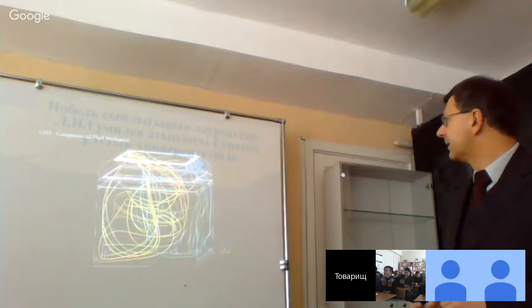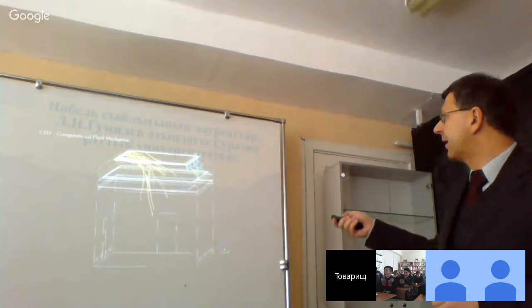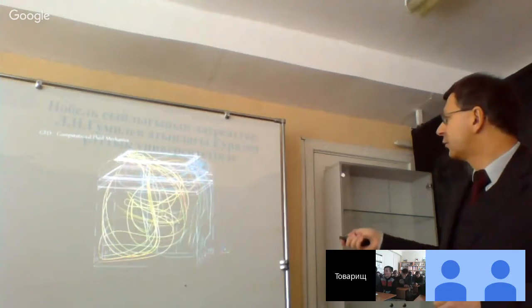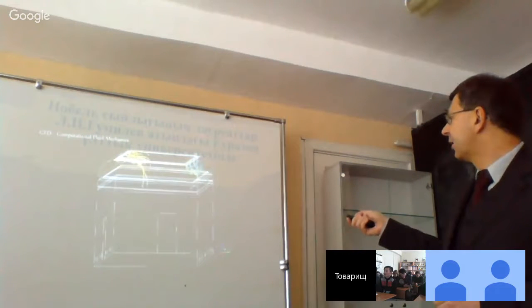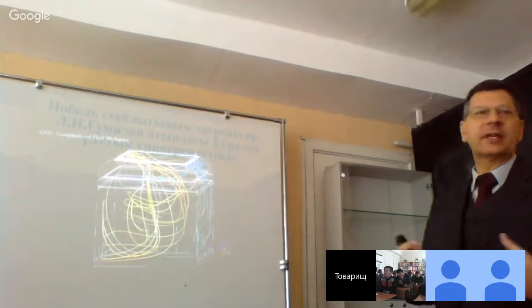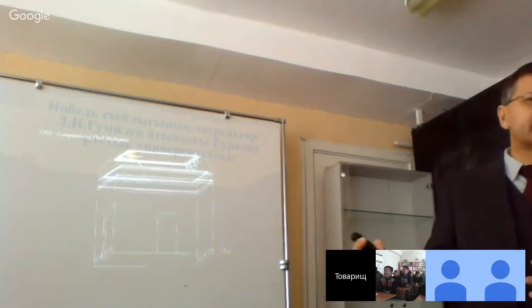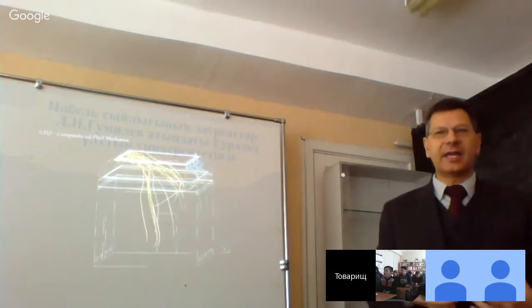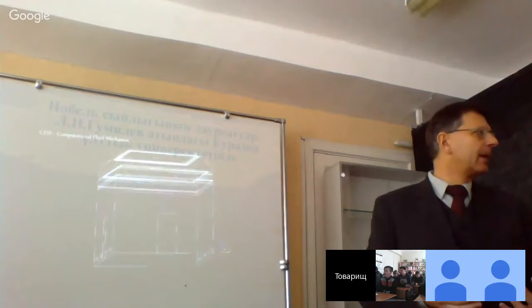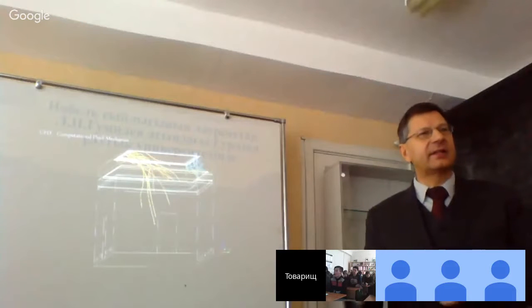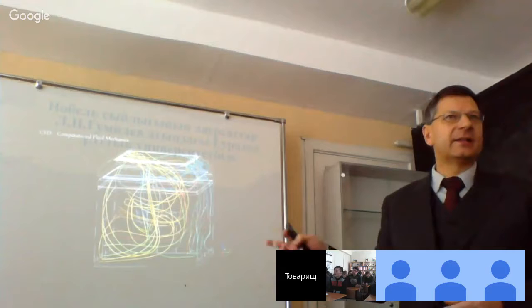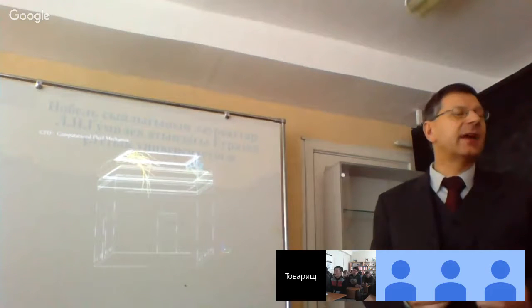You see the air comes near the ceiling into the room, the left side goes to the middle of the room, the right side flows along the wall down, and now you can analyze how well the system works, whether it is okay or not okay. And then you can change something, in a way that the system works the way you want. And the accuracy of this calculation is very high.